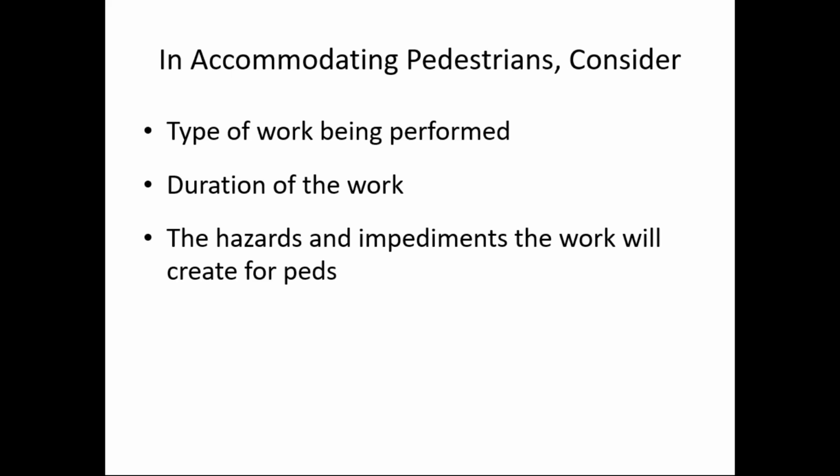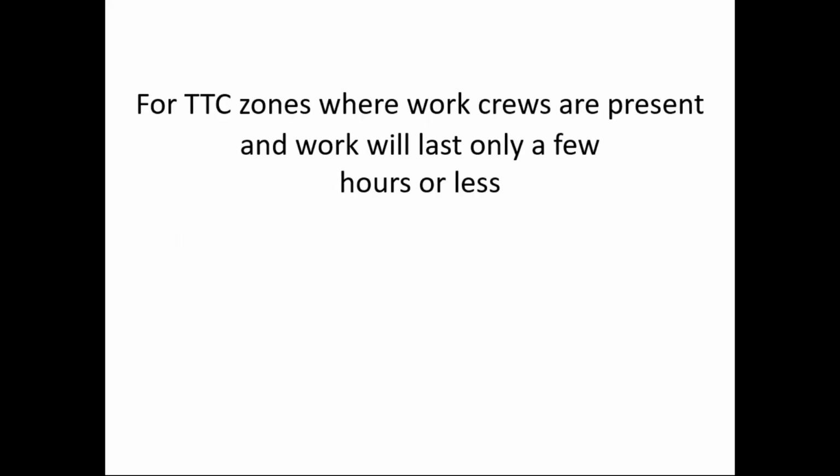Well, now let's get into the main topic of our session, which is how do we accommodate pedestrians in work areas? It's important, I think, to look at what type of work you are performing. What's the duration? Is it going to be a few hours or a day or a few days or a few weeks or maybe months for a bigger project? And then think about what hazards and impediments that work will create for pedestrians. Notice that impediments relate to accessibility, but hazards relate to safety. We have to consider both.